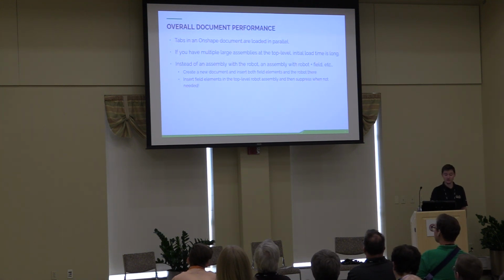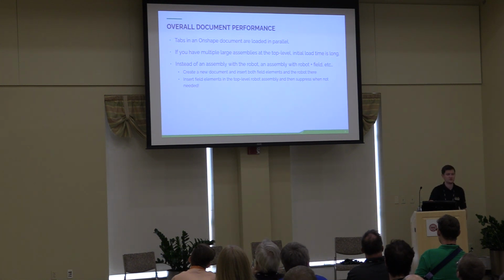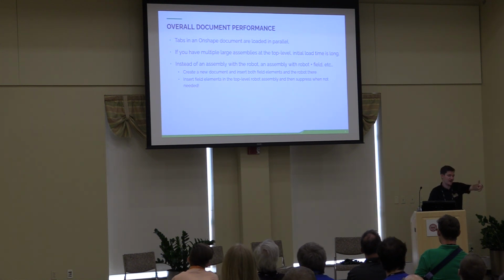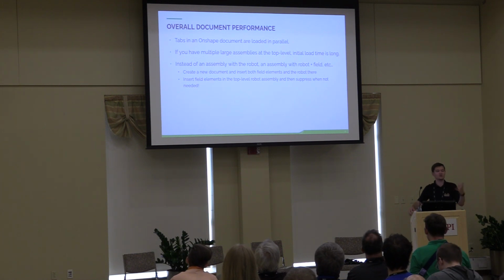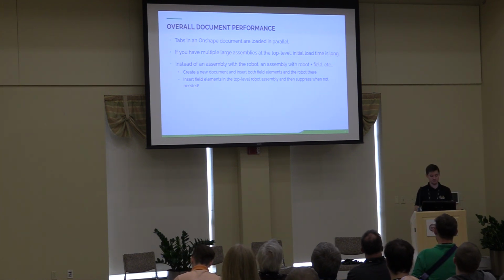Last thing, tabs are loaded in parallel in a document. I've seen teams set it up where they have their top level robot in an assembly, then another assembly that's top level robot with the speaker, top level robot with the amp, top level robot with the stage. Stage, yeah, what's the climb structure this year? Stage, there we go. Every time you do that, you are adding more load time to the entire document. So it's better to just put them in there.